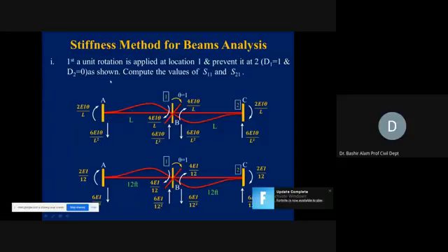Now, step number 1 of this 3 will be, we are allowing now rotation. Here you see at 1 now, which is support B. This yellow line, we are rotating it to this inclined red line by an amount theta is equal to 1, because rotation was unknown. So we are giving a unit rotation there.